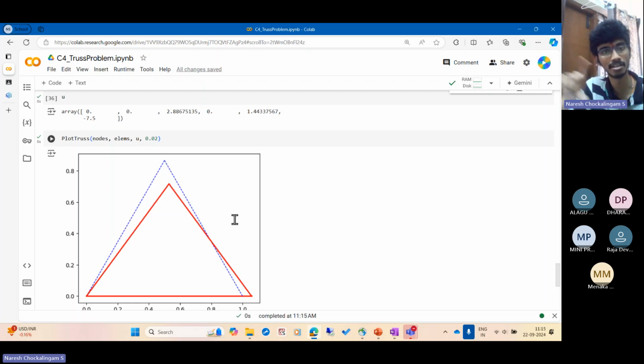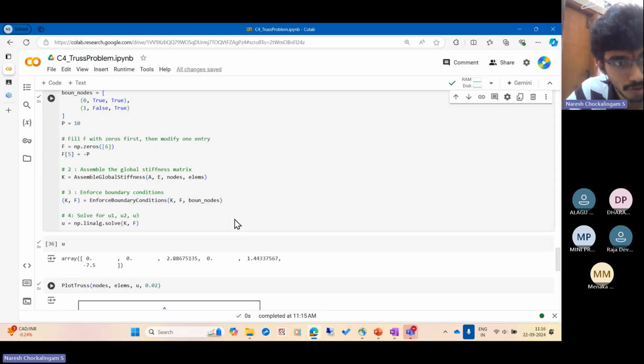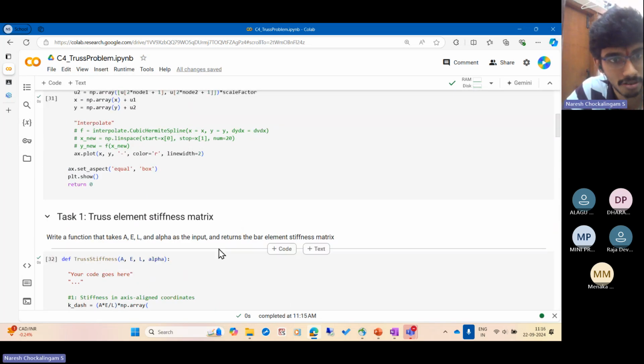If you have some workshop building or some industrial building, you'll have a roof truss. That will be a Pratt truss. You'll have parallelograms with one diagonal member like this. And on top, you will usually have some kind of sheeting. So approximate the loads of the sheeting by some point forces onto the panel points. Maybe some of you want to do a project by the end of the workshop, using all the concepts that we studied: trusses, frames, nonlinearity. You can do one such analysis. So use the codes that we developed.